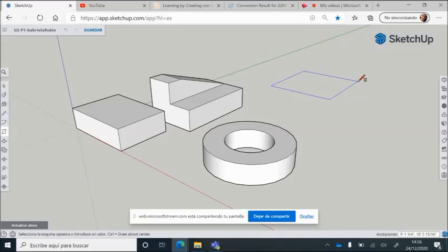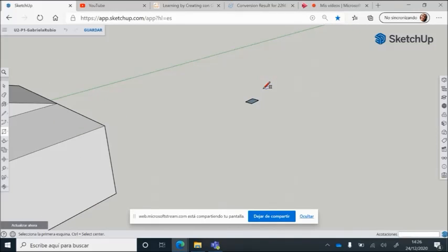So we just click with the mouse on the origin on the rectangle, and now we can type directly numbers that mean the measurements of the rectangle. So if I directly type 55,8 and click enter, I am going to have a rectangle with those dimensions, right?